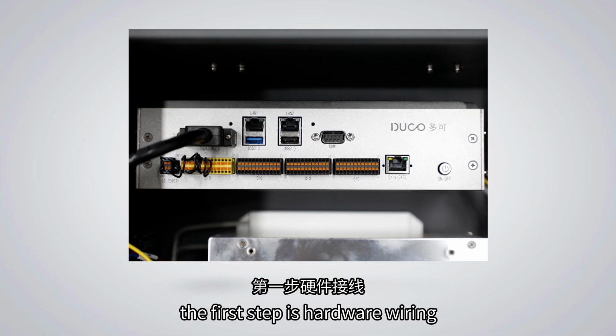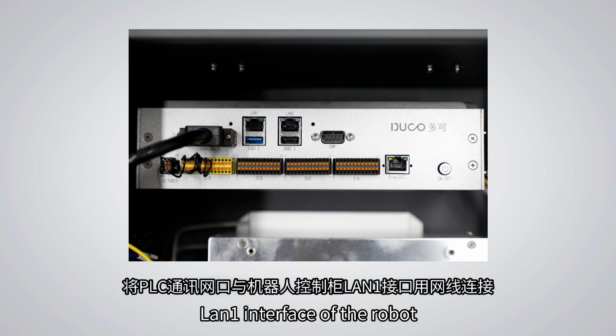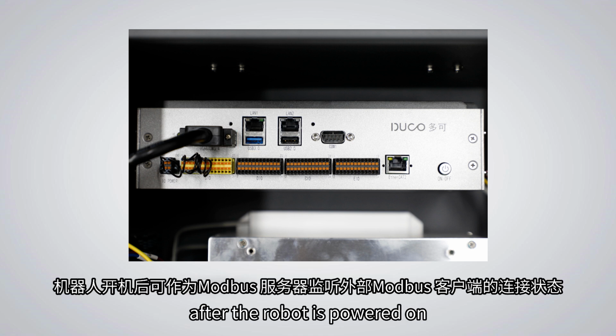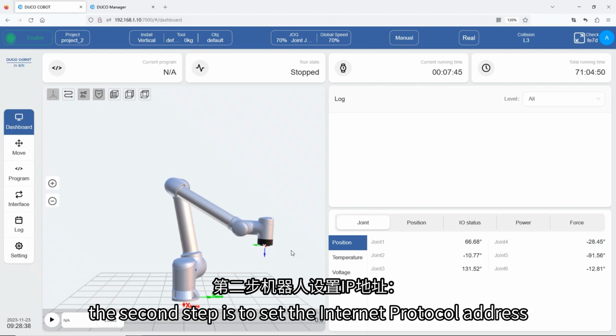The first step is hardware wiring. Connect the PLC communication network port with the LAN1 interface of the robot control cabinet with a network cable. After the robot is powered on, it can be used as a Modbus server to monitor the connection status of external Modbus clients.